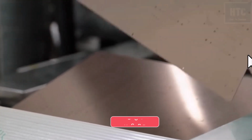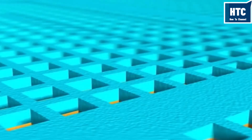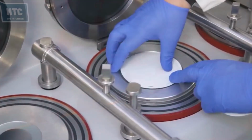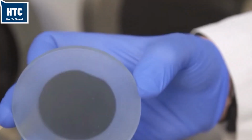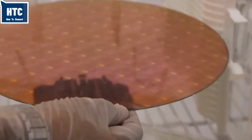In modern processors, we don't just lay transistors flat, we build them up. We create FinFETs, or gate-all-around transistors. We etch vertical fins of silicon, then deposit a high-K dielectric material over them to serve as the gate. This 3D structure wraps around the channel, preventing electricity from leaking when the switch is off.